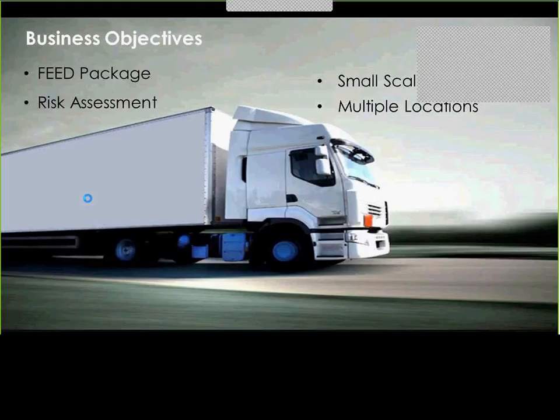The facility must be sized with a production rate to accommodate roughly 100 trucks, consuming 50 metric tons of DME per year. The plant's design must be able to be replicated in multiple locations across Canada, with consistent products being produced in each plant. And finally, the resultant product must meet the ASTM fuel grade standard of DME, which has a mass percent of 99.85.